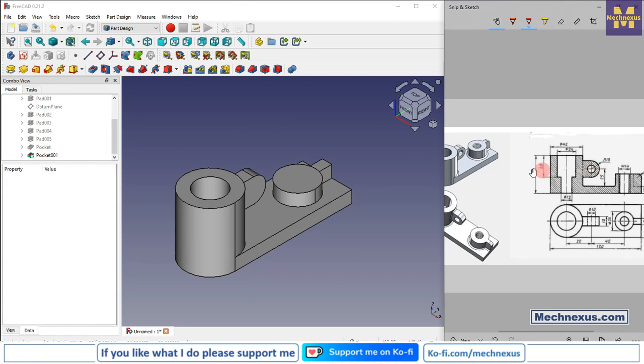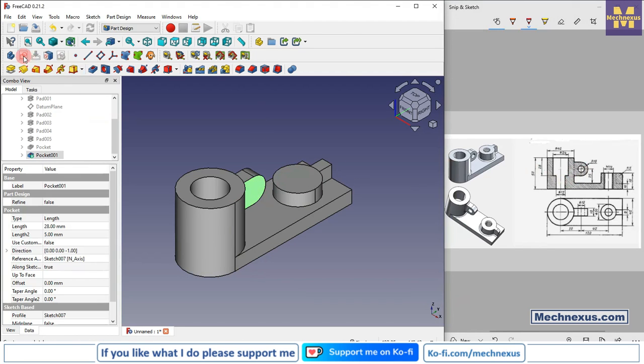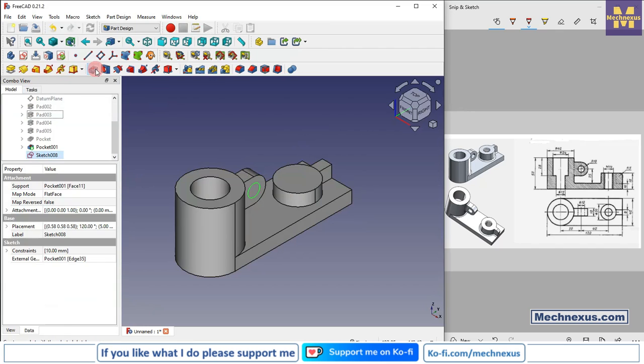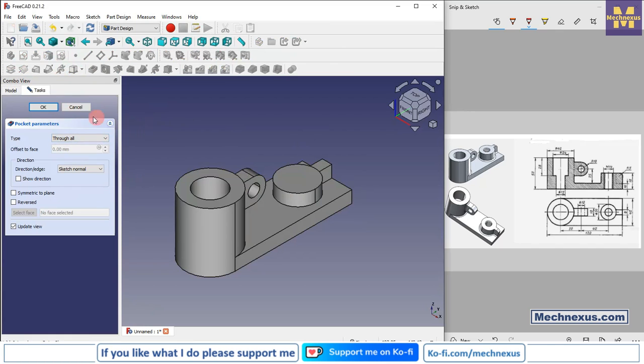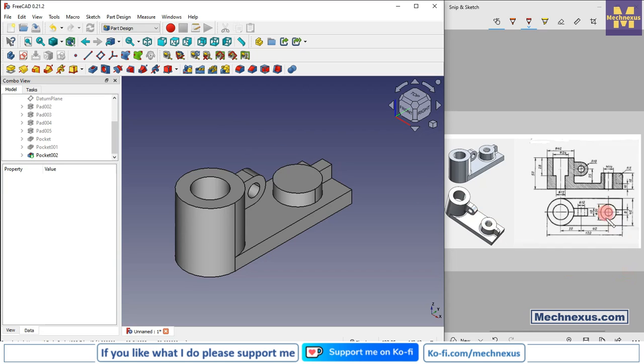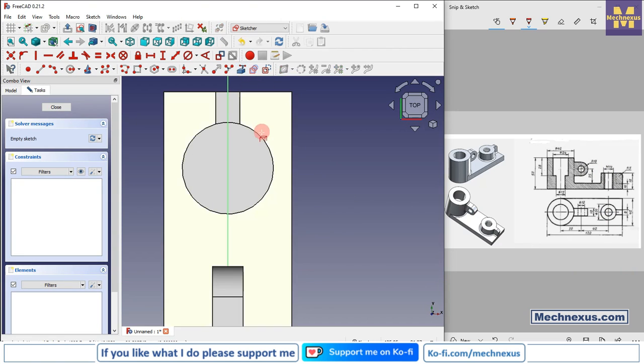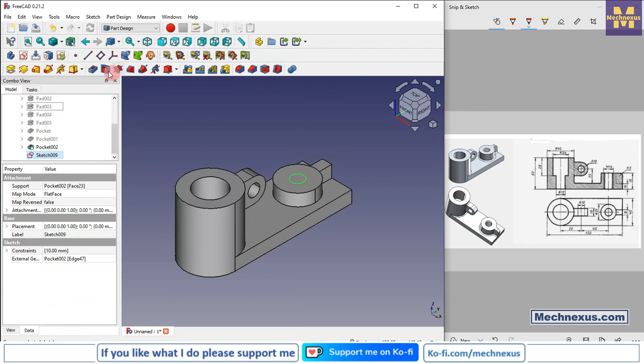Now we will create this hole. So we will select this face, click on the sketch, click on project geometry, select the circle, create a circle, and constrain it with a diameter of 10 mm, close it, extrude cut, and say through all, say OK. Now here we will create a hole of M10. So I will select this top face and click on the sketch, click on project geometry, create a circle, and provide it a diameter of 10, click on close, select the sketch, click on hole wizard,